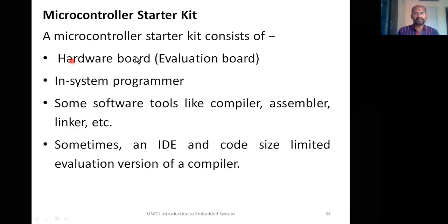Starter kits come with a hardware board, the evaluation board. Our Arduino board itself is this one. Then an in-system programmer. Generally, to program a microcontroller, we have to use a separate programmer. Whereas if we use these starter kits, that programmer is present within the starter kit. If you have an Arduino board, you don't need a separate programmer for programming the microcontroller; it is present in the Arduino board.